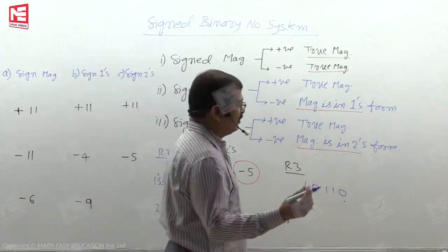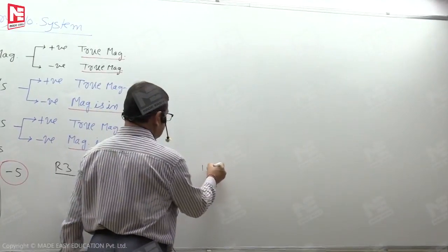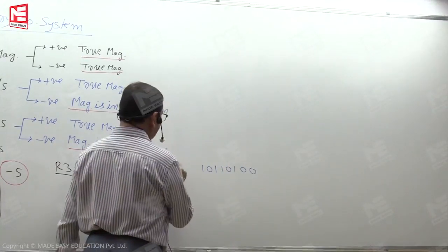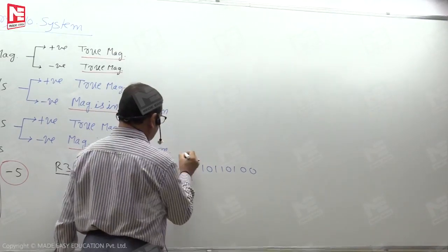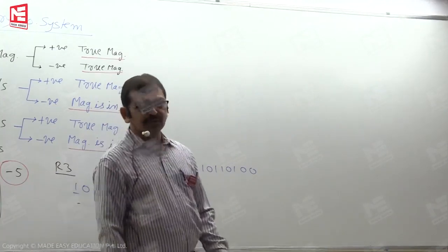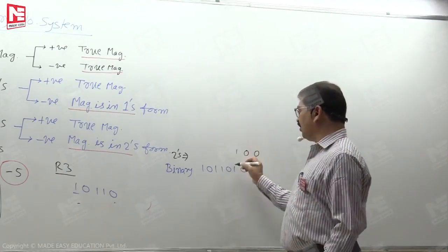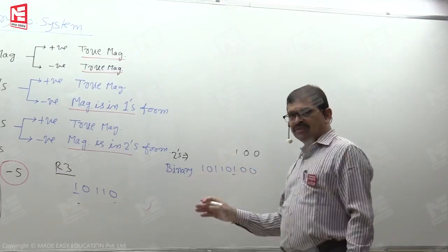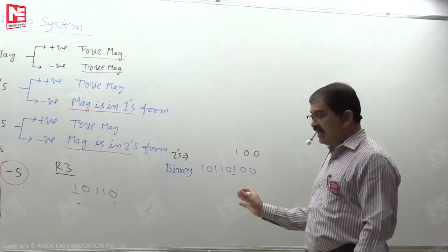To look at another example, suppose I have the binary number 10110100. To perform the 2's complement operation on it, we must read the bits as they are until we read the first bit that is 1, scanning right to left, that is LSB to MSB, not left to right.